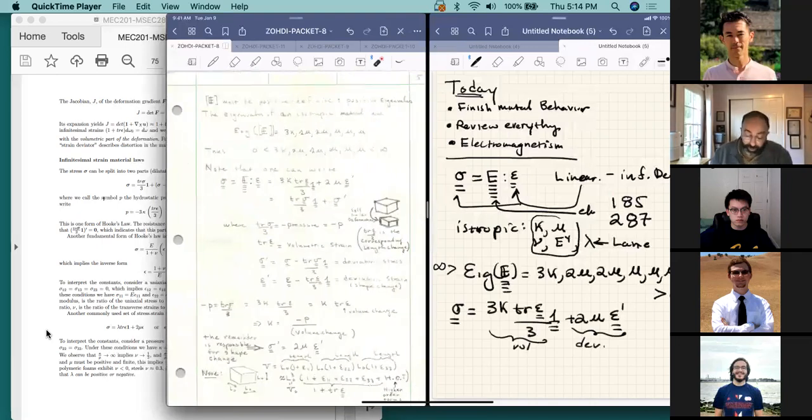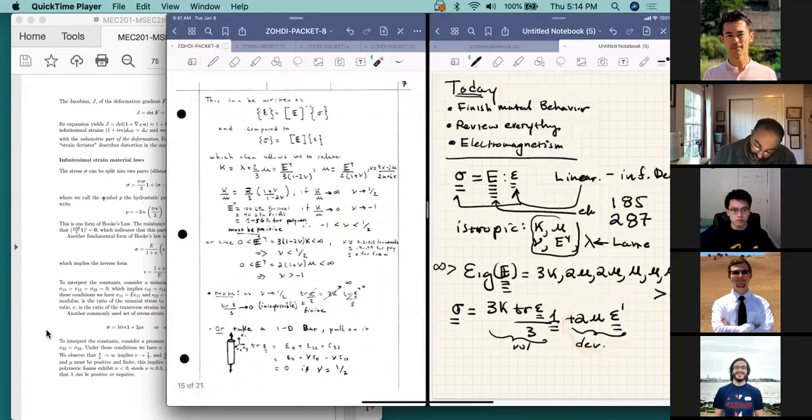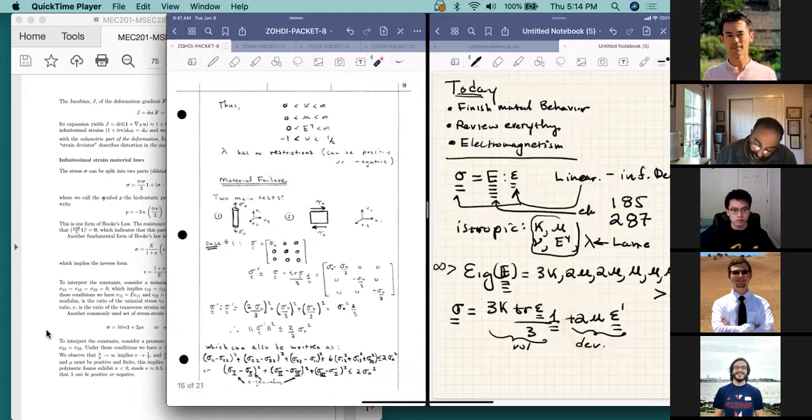Now, that becomes useful because later when we start to consider constitutive laws and failure, we'll see that the failure theories, in fact, are going to home in on exactly this component of the constitutive law. In other words, the failure laws, which we got to last time in class at the very end, basically focus on one thing. They focus on the magnitude of how big that deviatoric stress is. So the deviatoric stress, just as a recap, is this thing right there.